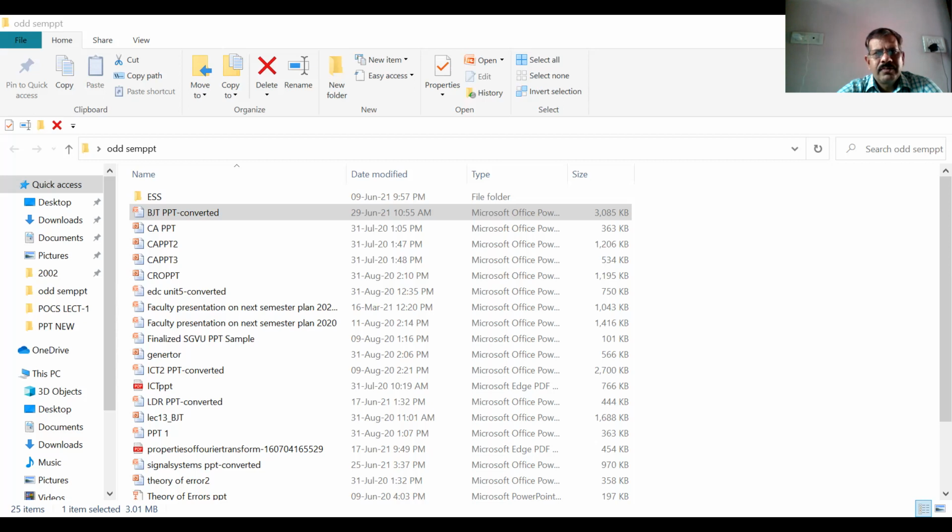So, working of NPN transistor. From this figure, this figure shows the working of NPN transistors. Forward bias is applied here to the emitter base junction and reverse bias is applied to the collector base junction in this diagram. The forward bias in the emitter base junction causes electrons to move toward the base.